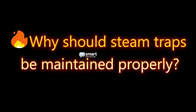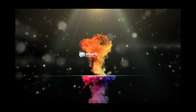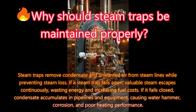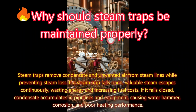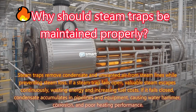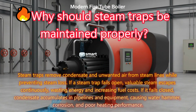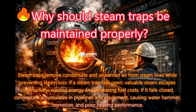Why should steam traps be maintained properly? Answer: steam traps remove condensate and unwanted air from steam lines while preventing steam loss. If a steam trap fails open, valuable steam escapes continuously, wasting energy and increasing fuel costs. If it fails closed, condensate accumulates in pipelines and equipment, causing water hammer, corrosion, and poor heating performance.